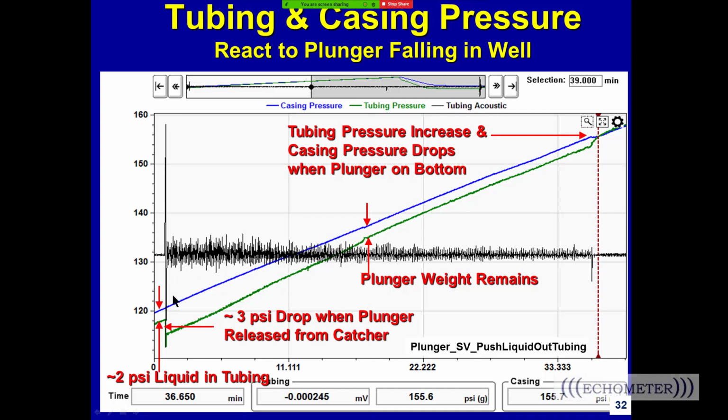And so from this point to that point, the plunger lift well is telling you that it needs a standing valve, because during shut-in all the liquid got pushed out and the plunger hit dry, and the casing and the tubing pressure equalized at the end of shut-in.